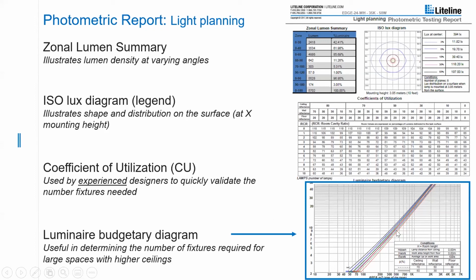So based on these charts, you can determine that you may need 8 lights for a space that is 320 square meters with a mounting height, and I'm sorry for the eye chart here, but it's expressed in meters: 4 meters, 5 meters, 6 meters, and so on. And there's a nice little chart. When you look at a full photometric report, this is very legible.